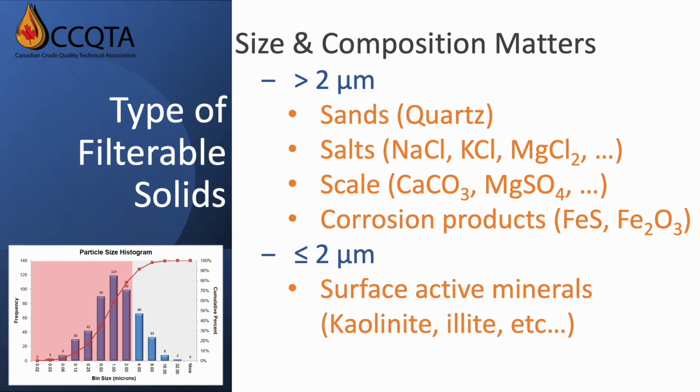They're not easily separated by gravity and they're very surface active, meaning they tend to bind with complex structures like asphaltenes and resins. This means they also tend to stabilize emulsion, so they reside in the emulsion layer and will not settle. When stabilized emulsions are present, they also tend to trap the larger diameter solids.